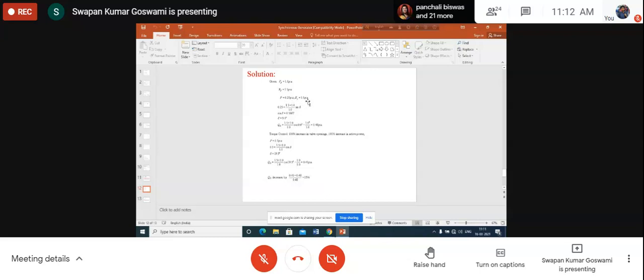These are given. So you can use the relation P equals EF Vt by Xs times sine of delta. P is given to be 0.25 per unit, EF is 1.5, Vt is 1, and Xs is 1. So sine delta you can calculate. Sine delta is 0.1667. Obviously, delta from here you can calculate. It is 9.6 degrees. Very simple. The given data, very easily you can do.